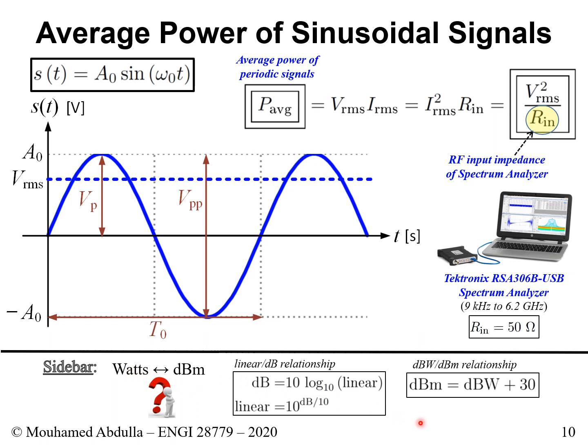Different people will show you different equations, but in reality, I think the most critical ones are these three. Anytime you work with watts, this is known as linear data. If it is linear and it's a power measure or a power difference, then you simply enter it into a log base 10 and multiply by 10, and that gives you the result in dB.